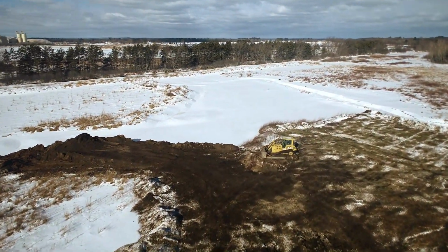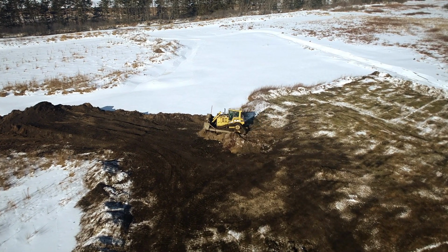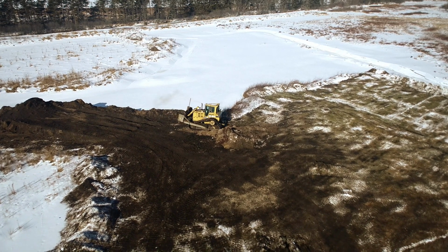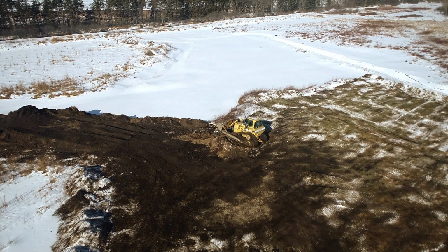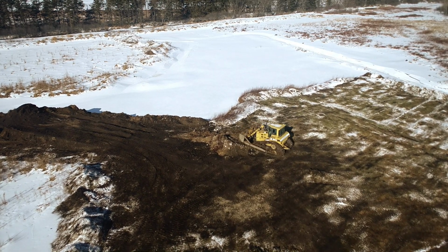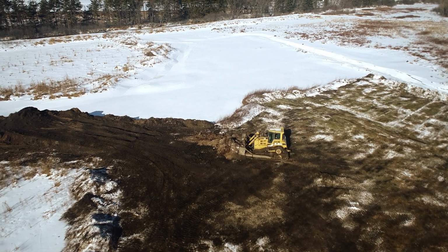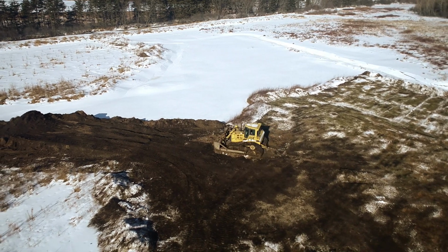Specific procedures for ripping. Complete a visual check inspection of machine and surrounding area. Complete a visual inspection of ripper shank and tooth before commencing work. Only allow the ripper shank to penetrate the earth to a depth of no more than 1 to 2 feet. Always rip in one direction and then rip in the other direction, creating a crosshatch pattern.